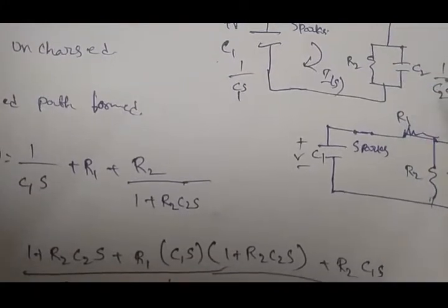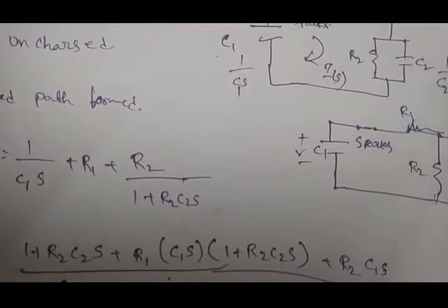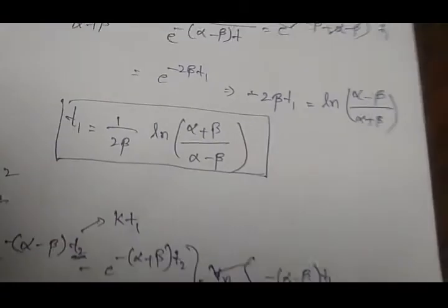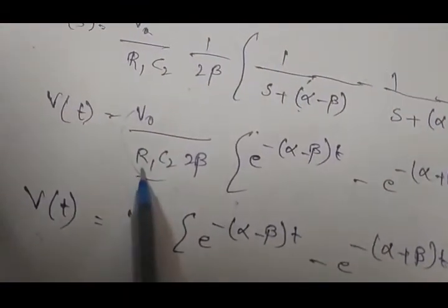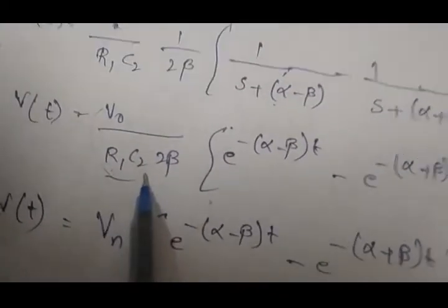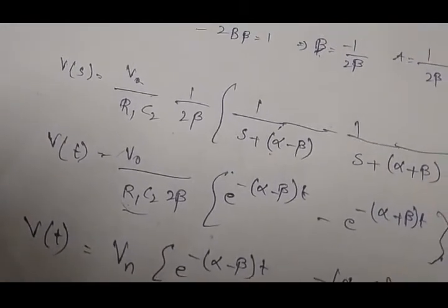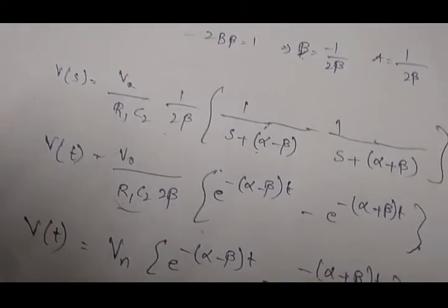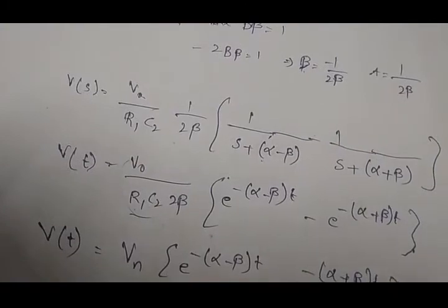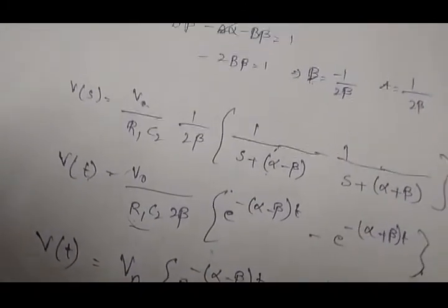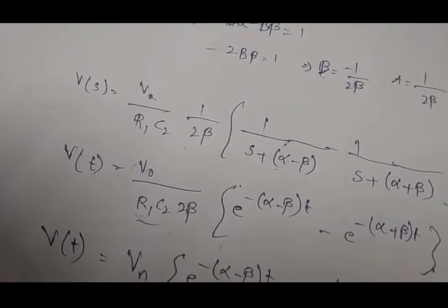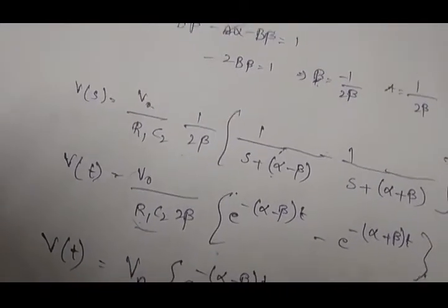Whenever the C2 quantity is varying, automatically the shape of your impulse changes, because your impulse expression depends upon your R1 and C2 values. So there will be an effect of the values of your C1, C2, R1 and R2. Mostly R1 and R2 are limited, and the ratio of your capacitors C1 and C2 is also limited.